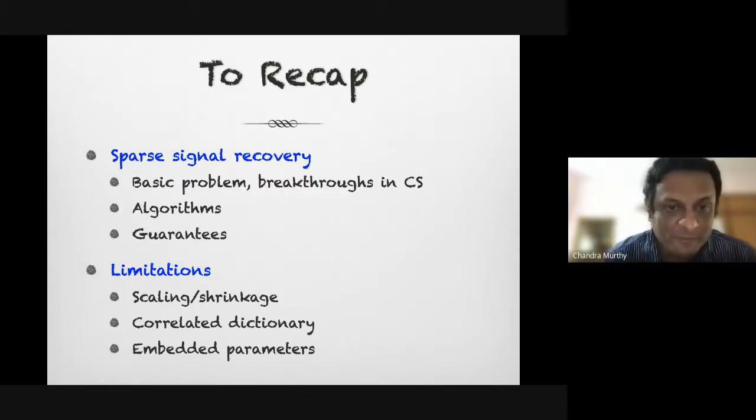So in wireless communication applications, oftentimes the sensing matrix is decided by the kind of pilot signals you use. So for instance, if you use pilot signals that are plus or minus 1 with equal probability, and you construct a measurement matrix out of that, then it's a measurement matrix that is known to you, but which has random entries. And you can use such measurement matrices for recovering sparse vectors or doing channel estimation.